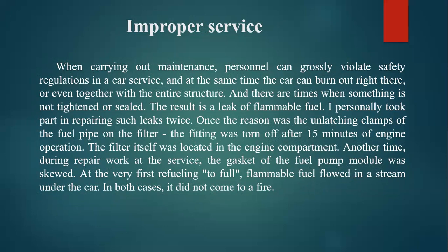I personally took part in repairing such leaks twice. Once the reason was the unlatching clamps of the fuel pipe on the filter. The fitting was torn off after 15 minutes of engine operation. The filter itself was located in the engine compartment. Another time, during repair work at the service, the gasket of the fuel pump module was not secured. At the very first refueling to full, flammable fuel flowed in a stream under the car. In both cases, it didn't come to a fire.